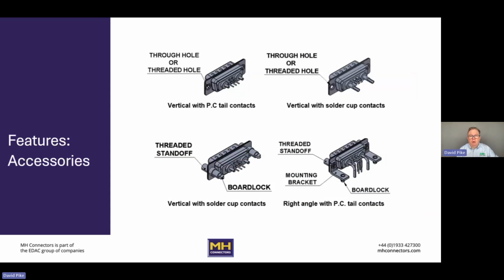There are a number of accessories that go with D subs. They allow you to mount on the front of the panel. They allow you to mount on the rear of the panel. There are PCB mounting versions. There are slide locks for quick release devices. Along with the design of the connector have come all of these accessories, all part of the standard.